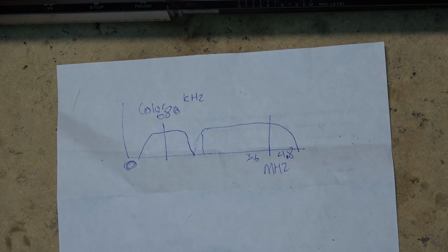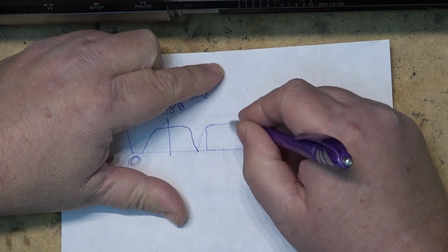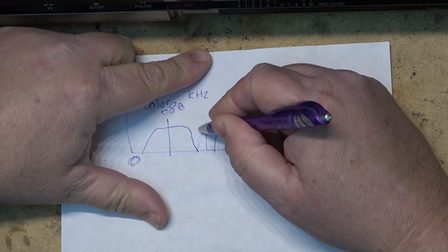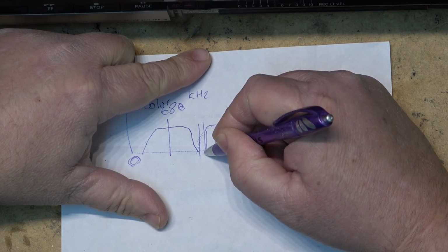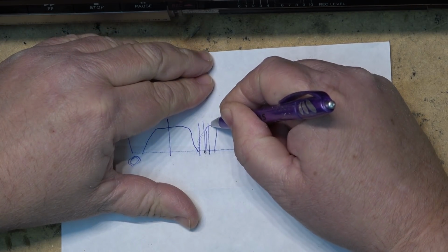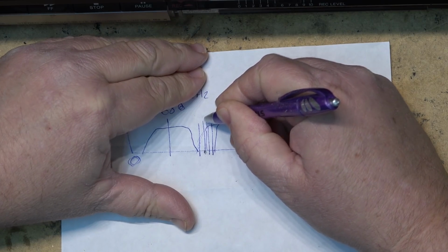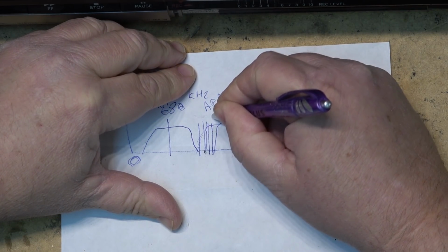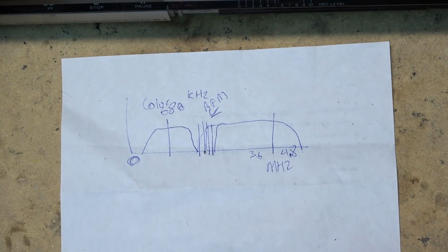And when they put the Beta Hi-Fi in, what they did is they rolled off the lower sideband a little sooner, and then they had room to put the 4 AFM carriers recorded by the same heads for the hi-fi audio.